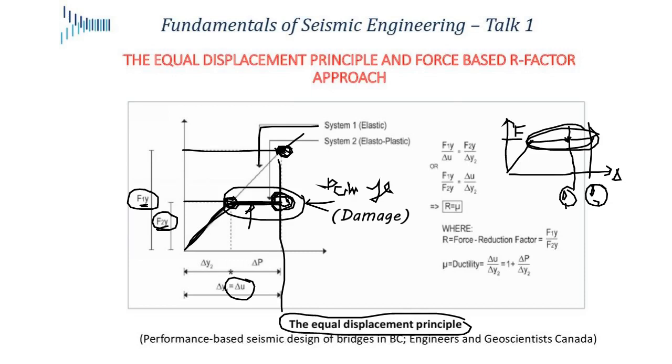But on purpose, we make certain parts of our structure weaker, and we know where those parts are going to be, and we know that those are the ones where the damage is going to occur. Okay, and then we do something with those parts of the structure to contain that damage. And those areas of your structure now act as fuses, because this force cannot go beyond this level. It cannot just keep climbing up. And what that does is it saves the rest of your structure from force overload. Okay? And I will explain that point in a bit more detail as we move forward.